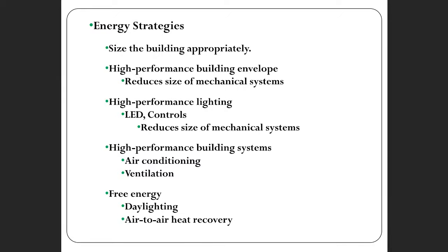That has to be removed by the air conditioning, which uses energy. So if we engineer a high performance lighting system, then we need less mechanical cooling to take care of that, right? High performance other building systems, air conditioning, ventilation. We also want to look at free sources of energy such as daylighting or air-to-air heat recovery.